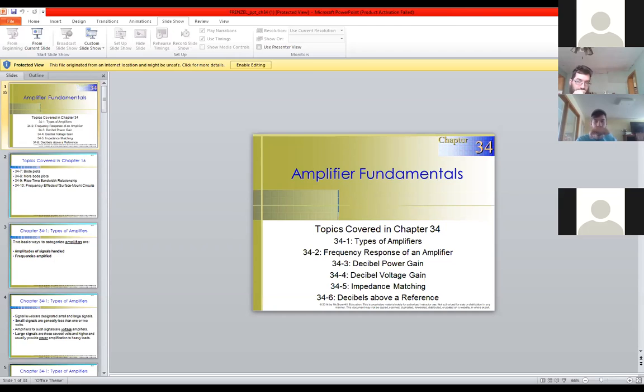You'll see here he specifies that a DC amp only has an upper cutoff frequency, so it will allow low frequencies to pass through or be utilized, if you will. And that's why we learned RC circuits and things like that, because that's what they use. We're going to use coupling and bypass caps to do cutoffs, and it'll allow us to pass through the bandwidth we look for. With an AC response or frequency response, you will have a lower limit cutoff, and you'll have, oh, yes, sir.